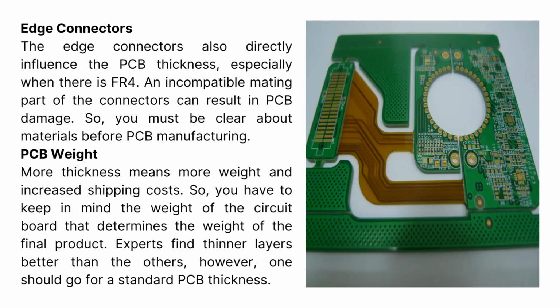Edge connectors. The edge connectors also directly influence the PCB thickness, especially when there is FR4. An incompatible mating part of the connectors can result in PCB damage. So, you must be clear about materials before PCB manufacturing. PCB weight: more thickness means more weight and increased shipping costs.